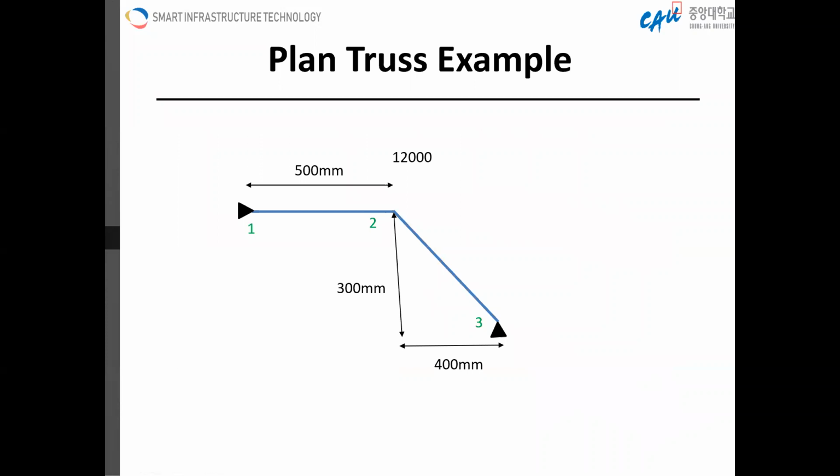I'm going to start with a plain truss example as a basic example to know the coding and language of OpenSees. How do they use the commands? This is a two element truss example with 3 nodes, and these are the element members, and we are going to apply a 12,000 force in the down direction at node 2.